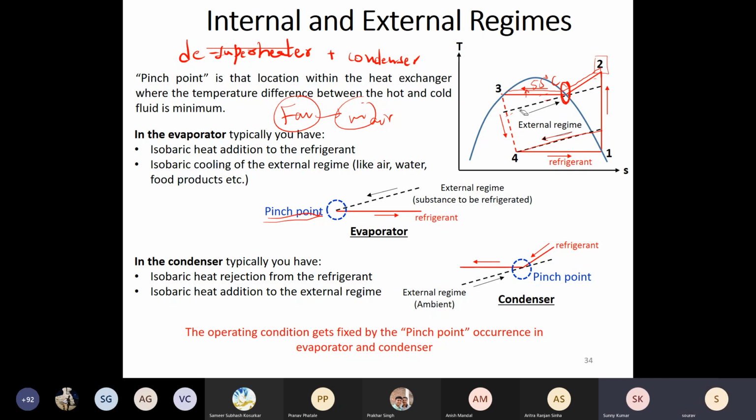Okay. Now, as soon as I shift from this point to this point, now you can appreciate, this is my line for which I will design. You can see now the cycle refrigeration effect has reduced. It has now become only this much. Because I had to maintain a finite amount of temperature at the pinch point, I could not follow this ideal line.